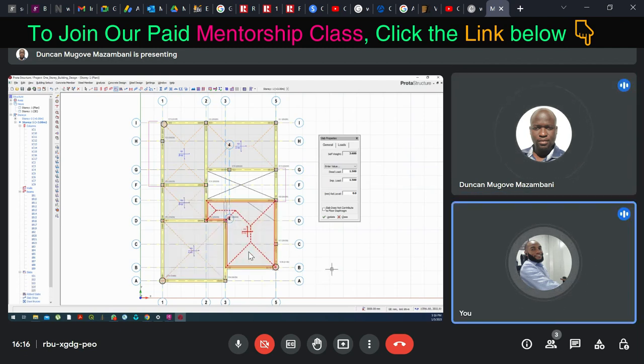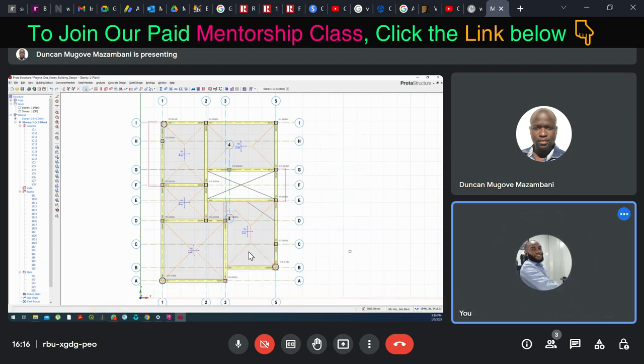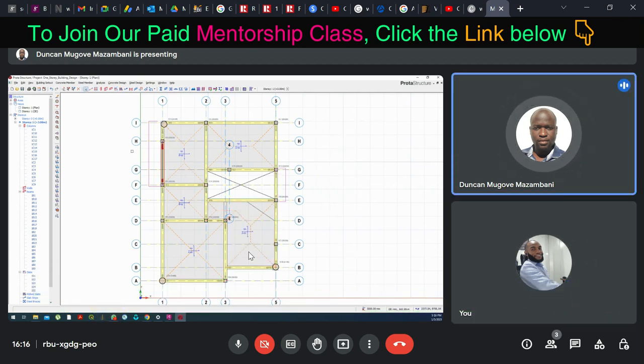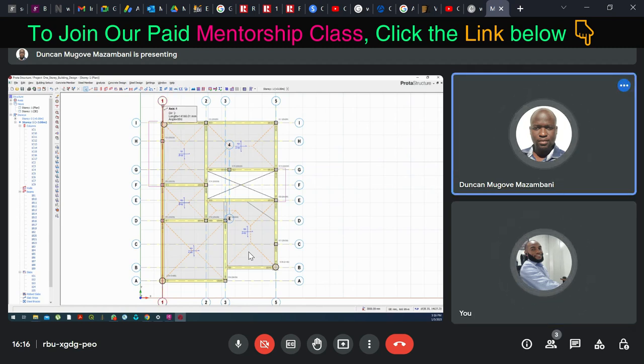Now click escape. Let's begin to model our cantilever slab, because we have a cantilever slab there, this portion and this portion. We have to offset grid line 1 to the point of the cantilever. You can see that the cantilever edge doesn't have a grid line.